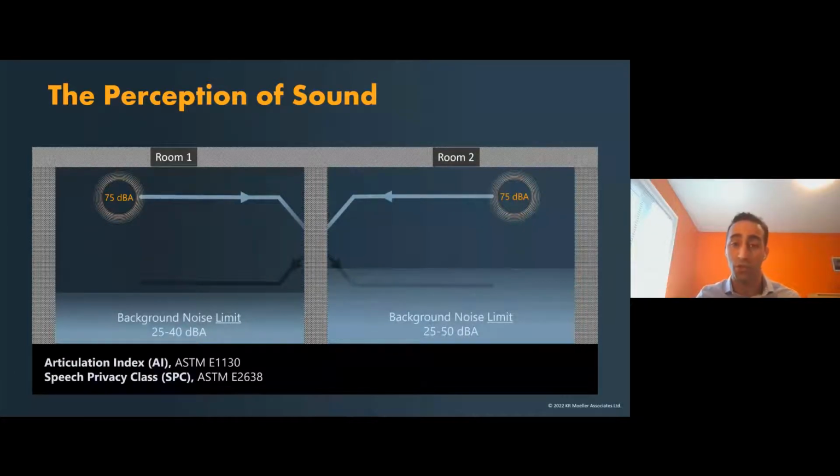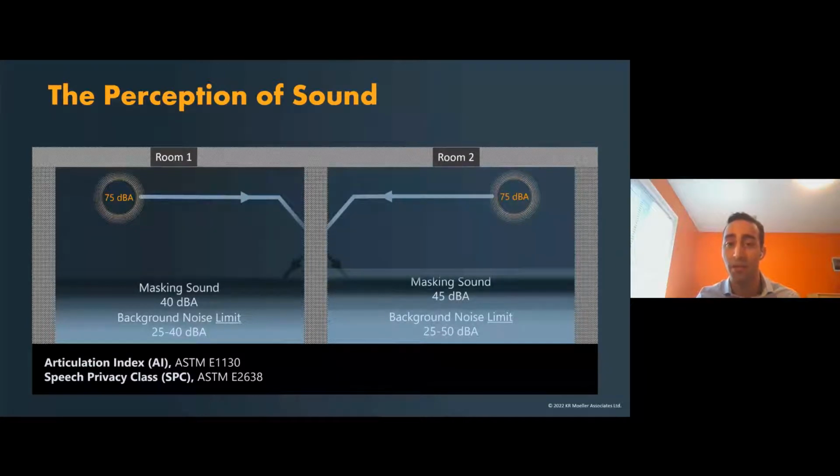One acoustical solution or strategy is to introduce engineered sound, to ensure the background sound level in a space is providing a minimum assurance of privacy. The use of masking sound allows us to greatly reduce the extent to which acoustic conditions change with respect to time and the environment. It is for this very reason that background sound is considered, and often referred to, as the most important parameter affecting speech privacy by experts in industry.